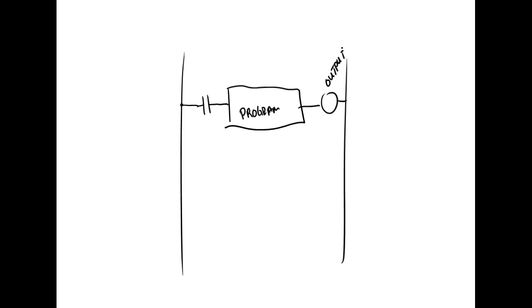Every time we start a new rung, it's automatically going to put a rung number over here for us. In RSLogix, it's going to automatically put a rung in here, and it'll start off at 0, and every time you insert a rung, it's going to number it. So rung numbers are automatically inserted on the side for us. We don't have to do that. The rung numbers start with 0.